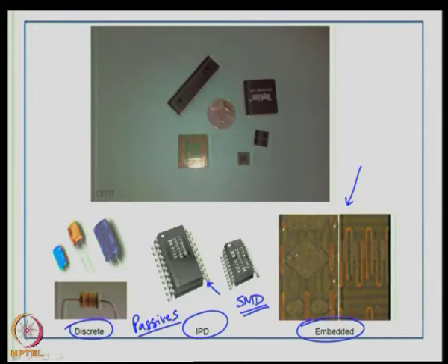Okay. So, this also eliminates the assembly process in your board. It will remove the 20 to 30% of board area or footprint area that you normally require for resistors and capacitors, and therefore, your board density can go up.